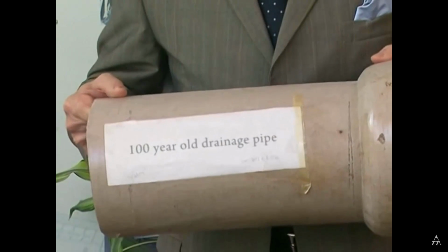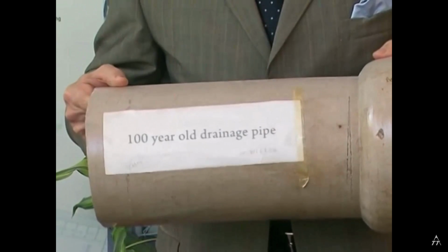The worldwide effort for the renovation and replacement of sewage pipelines has reached alarming dimensions. Repair or renovation is not always possible. At the latest, when the pipe is no longer sustainable in its structure or even hydraulically overburdened, it has to be renewed. Many pipe renewal projects are carried out using the pipe bursting method, thus without open trenches. This method comes along with an enormous cost advantage. Also, construction and traffic aspects, as well as resident interests, increasingly call for trenchless methods.